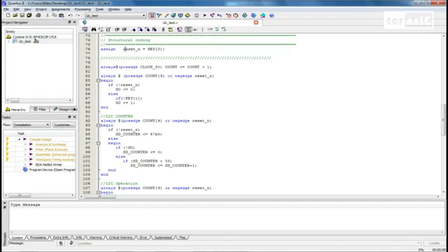Over here we can see that we've assigned our reset N to our key 0, and our always block on clock 50. Every time we have a positive edge of clock 50, we count up our 10-bit register of count. Since it's a 10-bit register, we can assign the 10th bit of the register as our clock for the entire system, effectively creating a very slow clock, slow enough for our I2C protocol. So our always blocks from now on will start with posedge count 9.